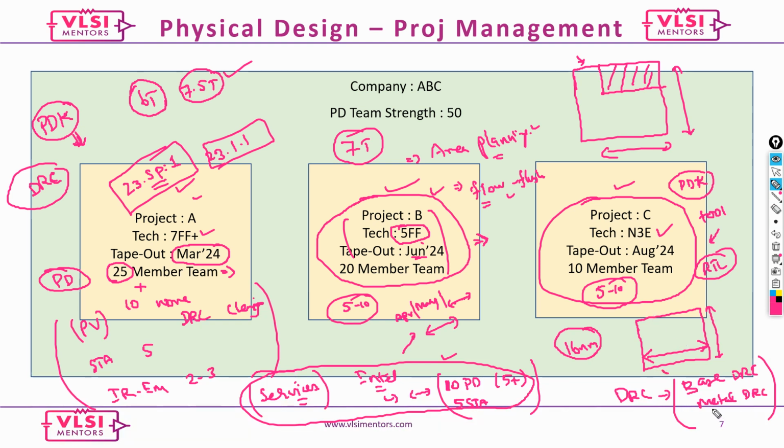Metal DRCs relate to your routing, so you can adjust them incrementally. So people have to meet the base DRCs at the floor plan stage itself. They have to follow the block integration guidelines and macro placement guidelines, and there may be checks that catch the issues upfront.